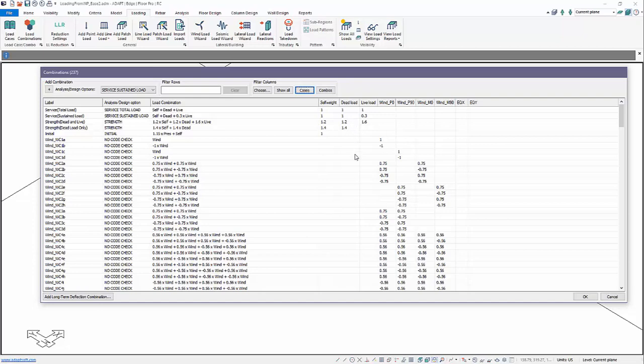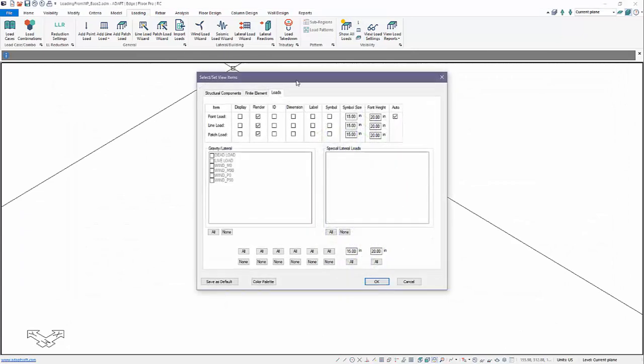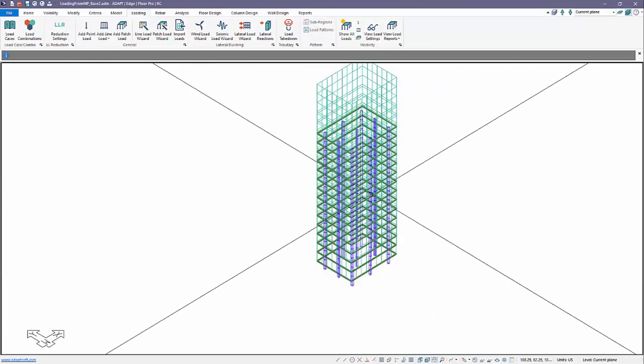You can write in the factors under dead load and live load, these two that are actually defined load cases. By defined, what I mean is if I go to the load settings, and then to patch load, I've actually defined loads as dead and live. Those were already assigned in this model.